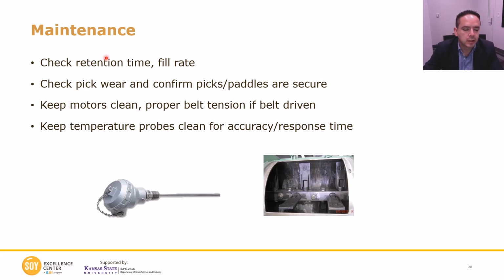You need to check retention time, which I showed you how to do. And also you need to check fill rate. And if you want to check fill rate, you just need to stop the conditioner and open it. And what I was telling you is that you need to make sure that you have like a mountain of feed inside the conditioner.